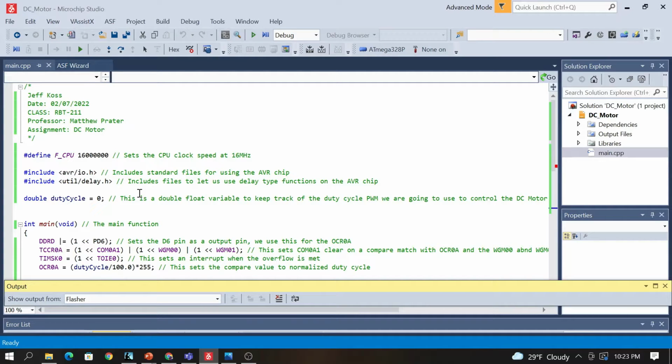It took me a little bit to get the hang of pulse width modulation, interrupts, and timers, because it was a different form of programming than straight up C++ or something like the Arduino. With a microchip, we're dealing with registers, and little tiny chunks of memory that are bits that make up bytes, and you have to manipulate those bits individually.